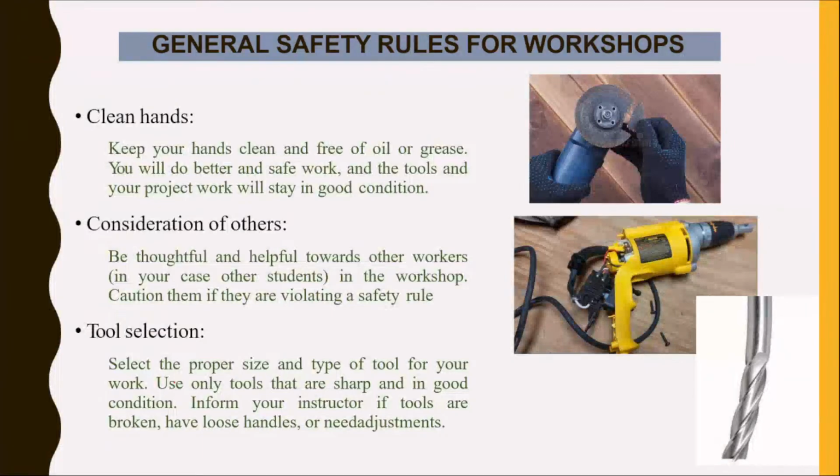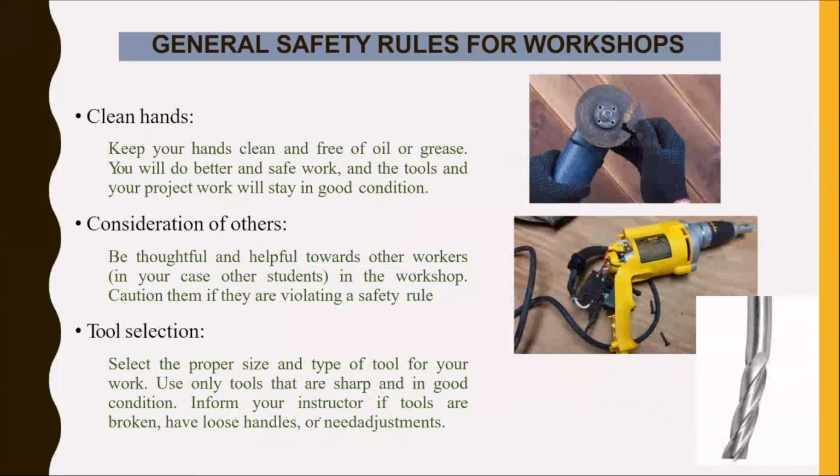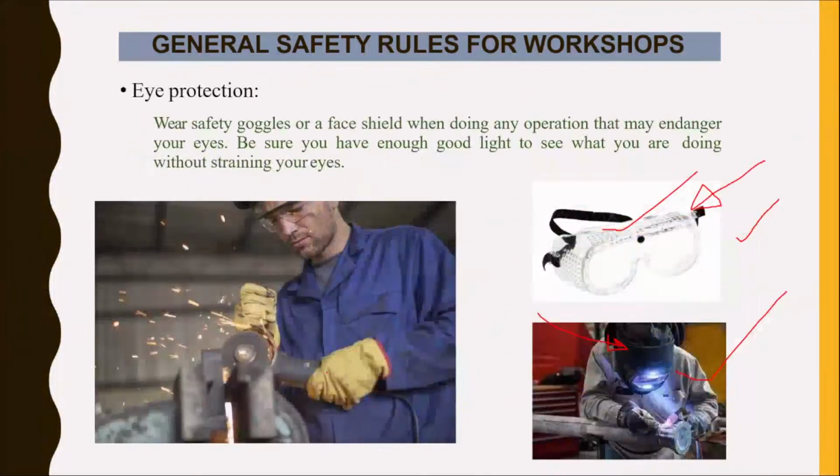You have to select proper tools for your application. Otherwise, it will be hazardous. Carrying tools. Keep edge pointed tools turned down and do not swing your arms or raise them overhead when carrying them, right? You can use this kind of apron to carry your tools safely.